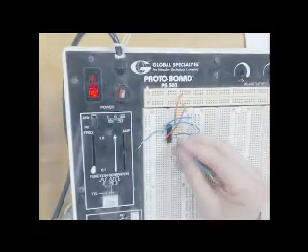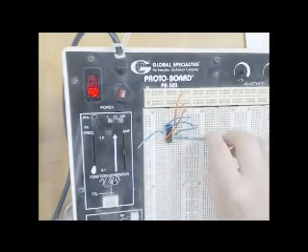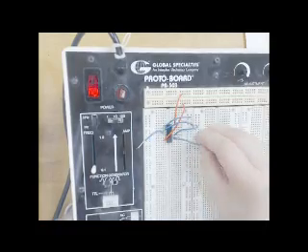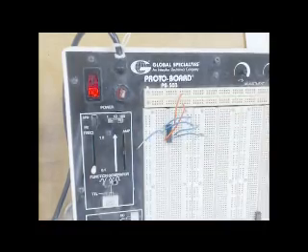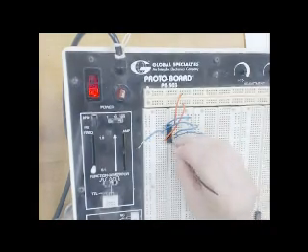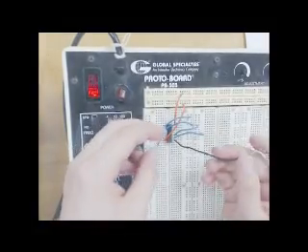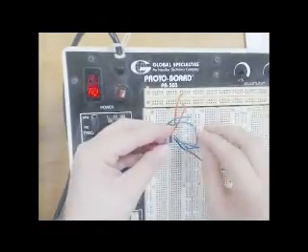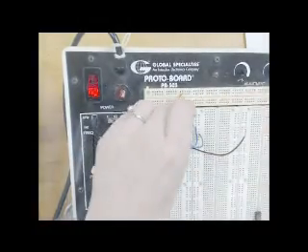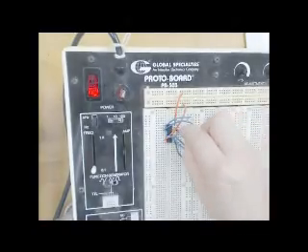and D, feeding into another AND gate, D. And then the output of this, which is this black wire, representing C and D. So here's the output for A and B, here's the output for C and D, and then what we're going to do is combine these both into one more logic gate, one more AND gate. So we're going to have A and B and C and D.